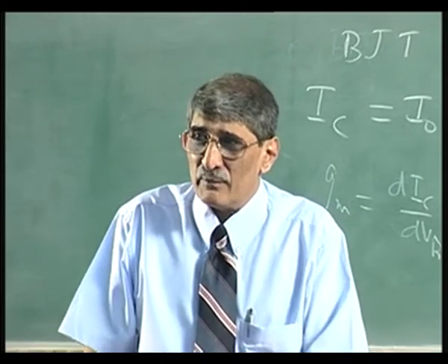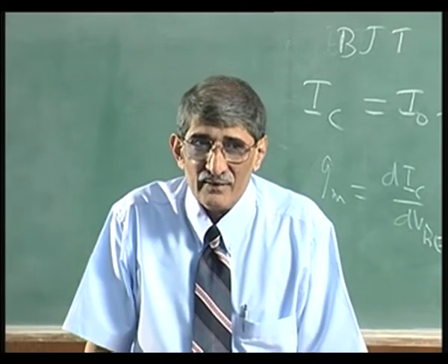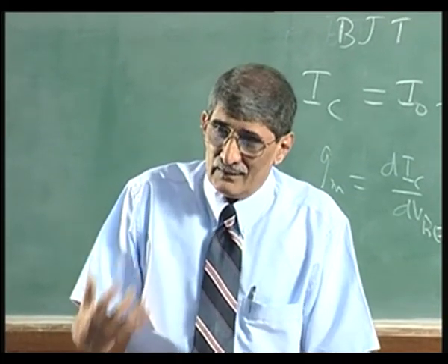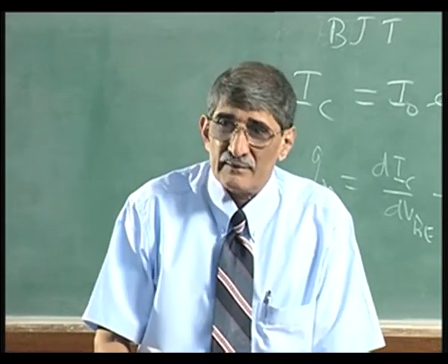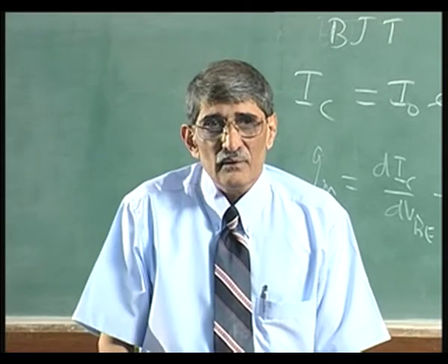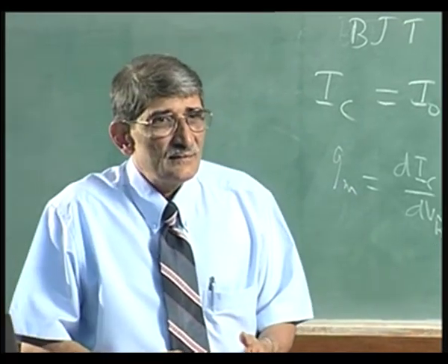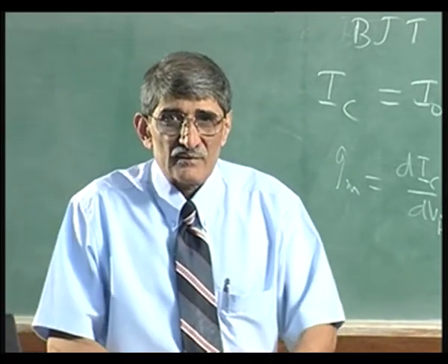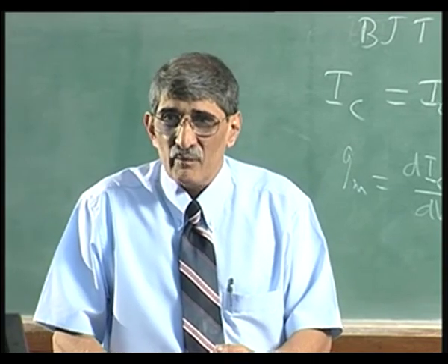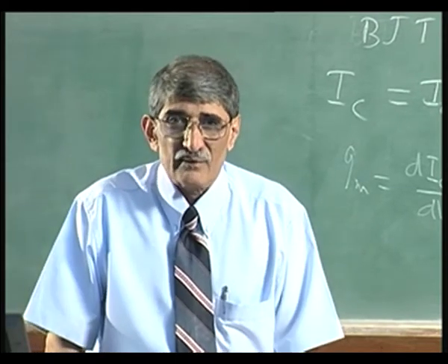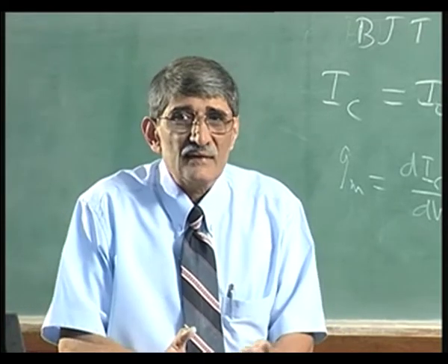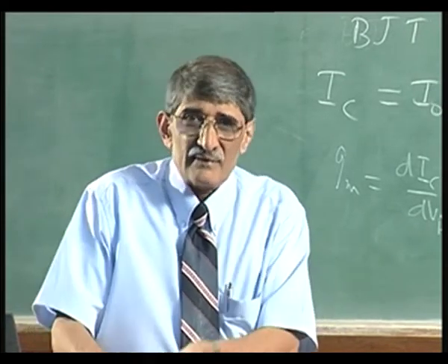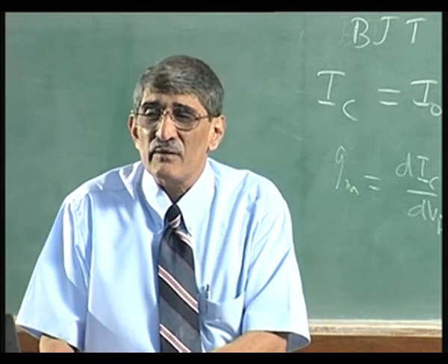Bipolar, though it is a slower device by itself, is faster in its ability to charge subsequent capacitive loads. So, in an integrated circuit, between bipolar and MOS type of devices, the bipolar circuit is faster because of its ability to charge all the capacitances. Ultimately, as I keep on shrinking the device size, it is a capacitive load. Where does the capacitive load come from?